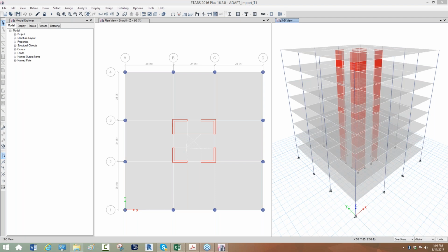If we try to import, let's say, response spectrum type results from Etabs, results that are not in equilibrium, we cannot apply those in ADAPT-Builder because the loads are not in equilibrium, so we get an error if you try to rerun, for example, a single level analysis using those imported loads. So that is one limitation. It's really used currently for lateral static and gravity loads.